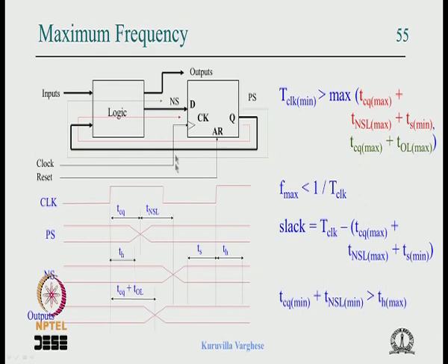So we are not, like in the clock period analysis, going from one clock edge to the next clock edge, but in a hold time violation we are considering the same clock edge. Like, a clock comes, the previous data has to remain there for some time, and we are working out, because of the same clock edge, how fast the data here changes. It propagates here, it propagates there, and it changes there. That is why the clock period is not there.